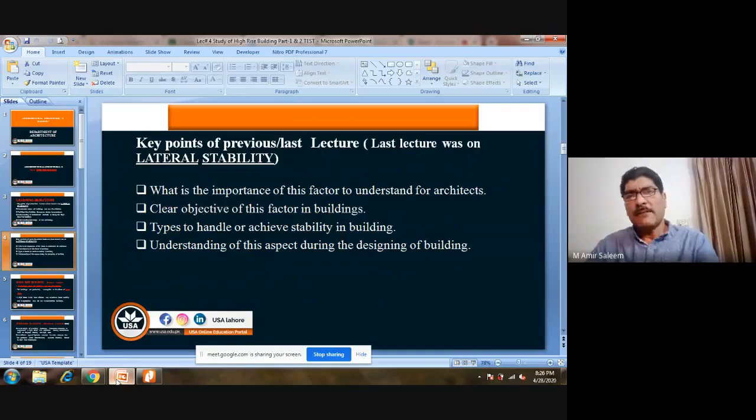In the previous lecture, we discussed some methodologies. Number one, the shear walls. This is one of the easiest ways, and we discussed in detail what shear walls are. And then we have braced styles to save against lateral movement for lateral stability. We have diagonals, we have K shapes, we have knees. So we have different styles to keep the building in a very stable condition and safe from lateral movement.